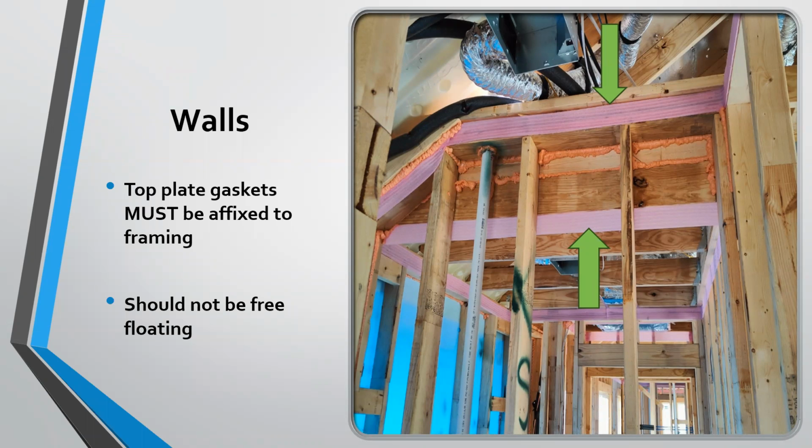So when it says exterior walls, there are some builders that say, well, that doesn't include interior walls. I don't have to air seal those because that's not what the code's intent is. The code's intent is anything that separates or is the junction of interior to unconditioned to conditioned spaces. That includes the top plate, that includes knee walls.